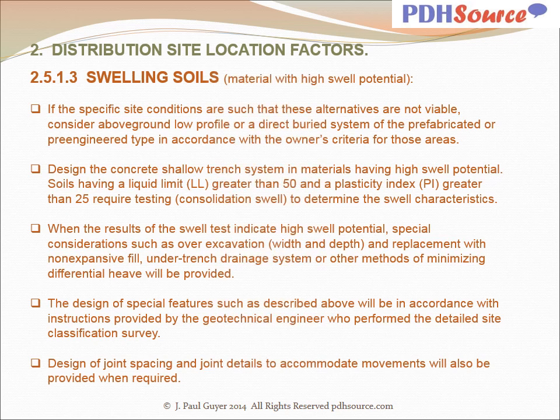In swelling soils, if the specific site conditions are such that these alternatives are not viable, consider above ground low profile or a direct buried system of the prefabricated or pre-engineered type in accordance with the owner's criteria for these areas. Design the concrete shallow trench system in materials having high swell potential.